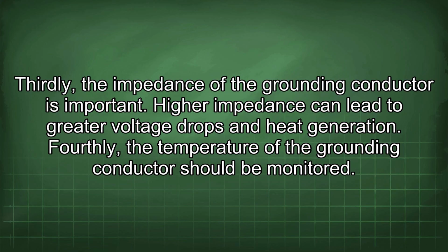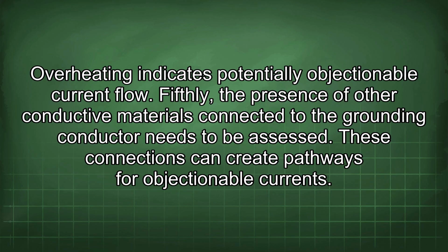Fourthly, the temperature of the grounding conductor should be monitored. Overheating indicates potentially objectionable current flow. Fifthly, the presence of other conductive materials connected to the grounding conductor needs to be assessed. These connections can create pathways for objectionable currents.